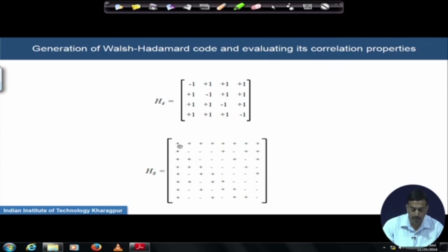Basically we need a kind of pseudo random sequence, but this is a sequence of all ones, so if we multiply it with a data bit, there is no change, or essentially no spreading occurs. So usually this first row is a redundant row, but then there are other properties which are of interest. To begin with, all rows will have autocorrelation